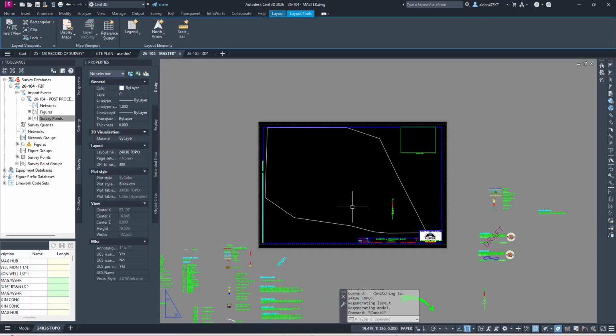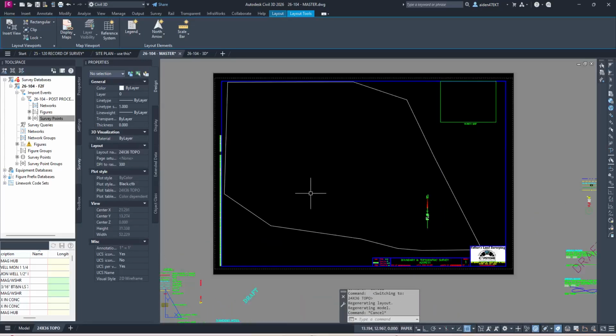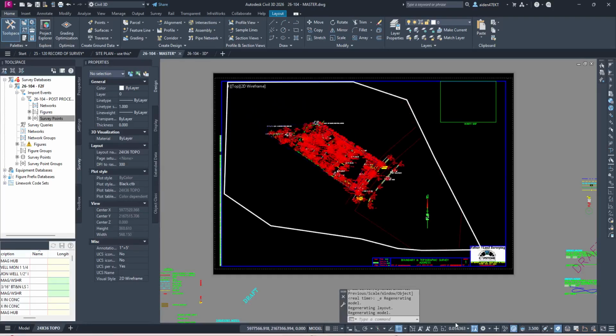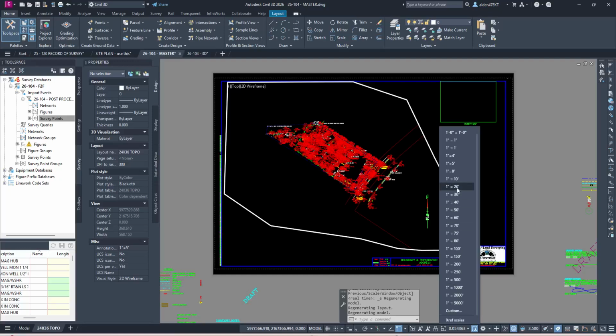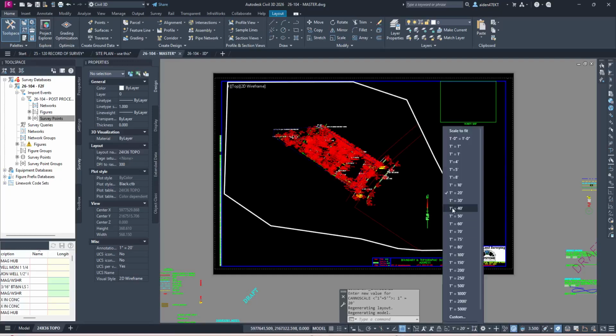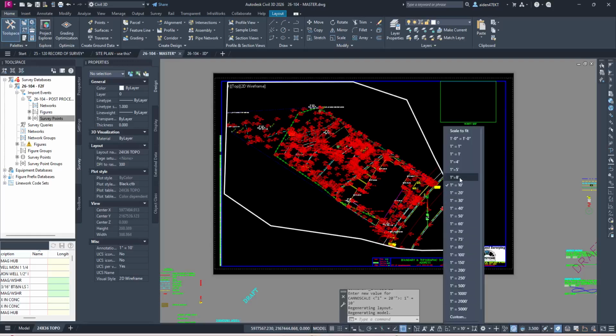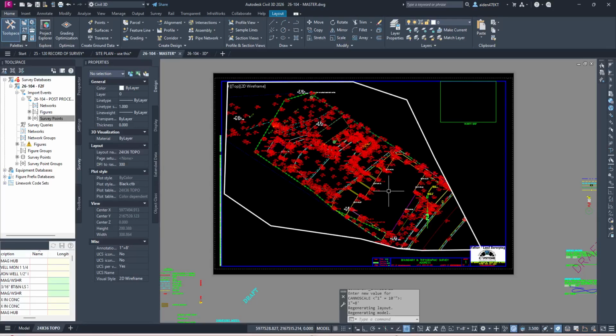Let's go over to paper space here. Let's double click the middle button, the scroll button, to zoom extents. Let's try probably a 20 scale. We can go in more, a 10 scale. Maybe we can get away with an 8. Architects like 8 scale. You can ask them why.